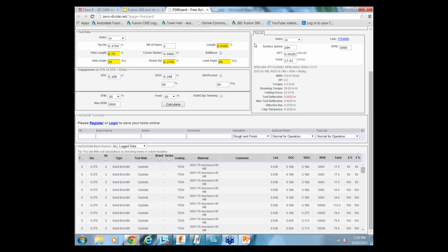So weren't you concerned that some minimum feed rate would actually cause rewelding of the chips? Typically, the faster you go, you can re-weld chips with the faster feed rates. Though typically the Tormach, it really happens because of excess spindle speed. The machine doesn't have the ability to get to the feed rates that would cause problems there. You'd be up in like the 45, 50 inches per minute kind of feed rates to get rewelding chips. Spindle speeds, on the other hand, if you're going too high of an RPM with too low of a feed rate, you're going to cause the same problem, just in the opposite direction. It's kind of like a bell curve, like up this way and down that way.